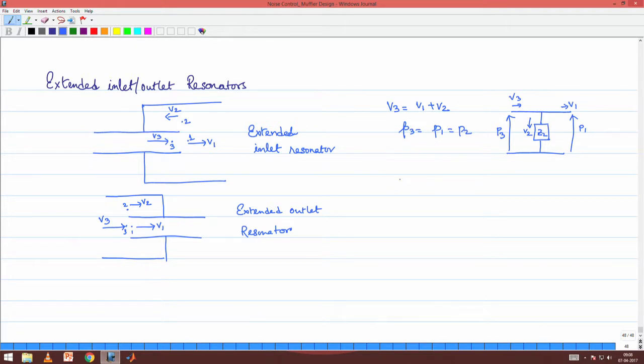So, this is where the point of difference lies. So, let us quickly do that. I will do it just for one configuration and the other should be pretty easy. Please understand that the walls of this duct are rigid, right. So, all along we are assuming that all the structural walls are thick and rigid. If not, it would lead to vibration of these structural surfaces, which would emanate sound again, and that form of sound radiation will be called breakout noise. But here we are dealing with the situation that the structure is fairly rigid and does not vibrate in response to these acoustic pressures.